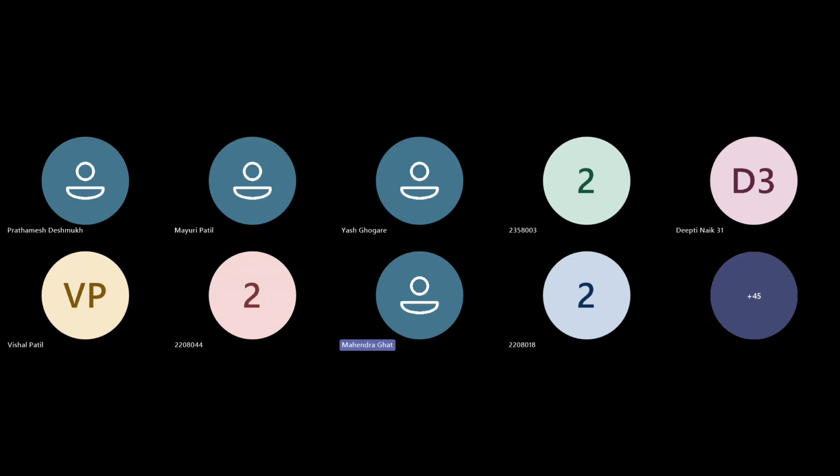But as you said, you are not getting output, so there may be a possibility that the switch is not getting turned on or off by the gate pulses you are giving. Now how you are giving the gate pulses and what the gate pulse requirement of that switch is, we have to see.